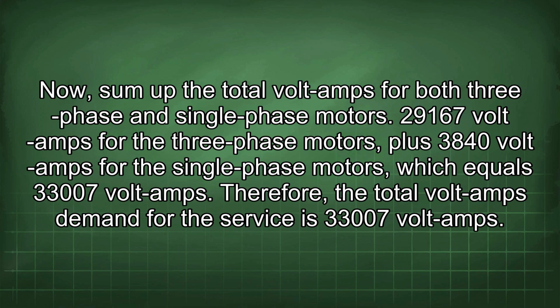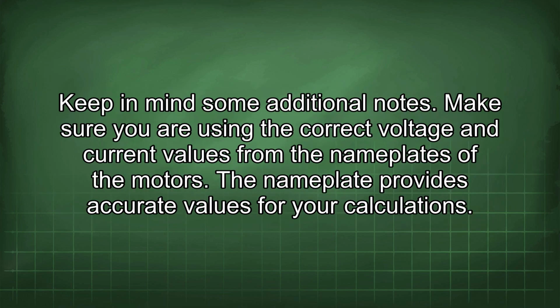29,167 volt amps for the three-phase motors plus 3,840 volt amps for the single-phase motors, which equals 33,007 volt amps. Therefore, the total volt amps demand for the service is 33,007 volt amps. Keep in mind some additional notes.